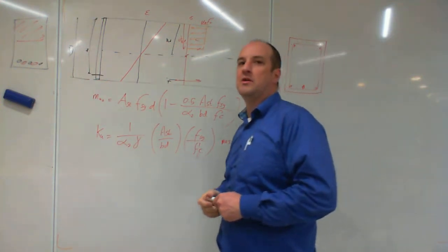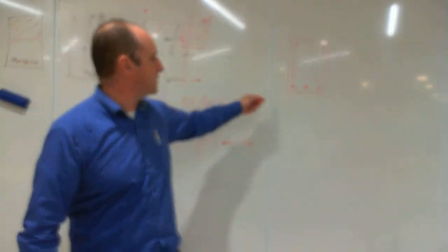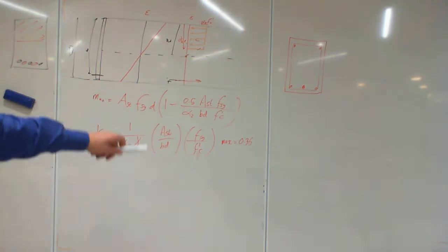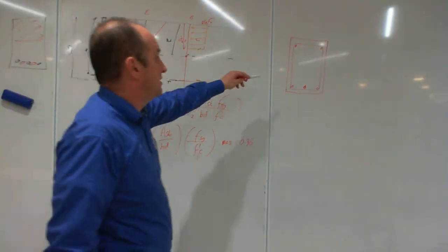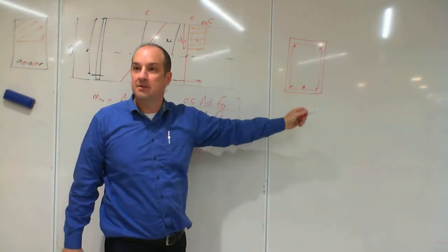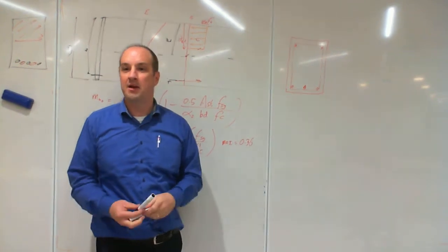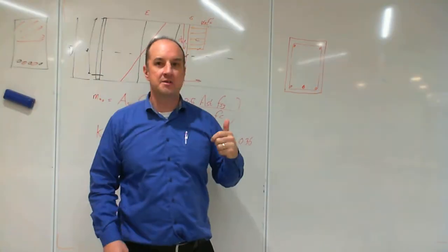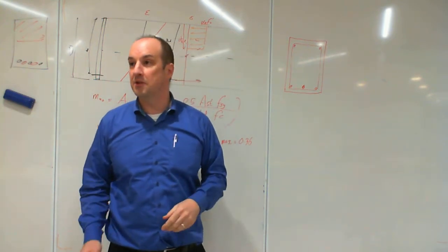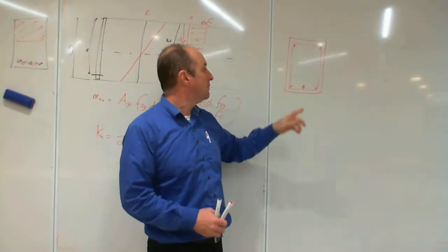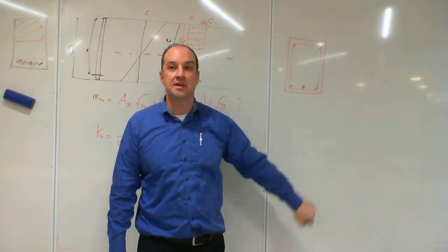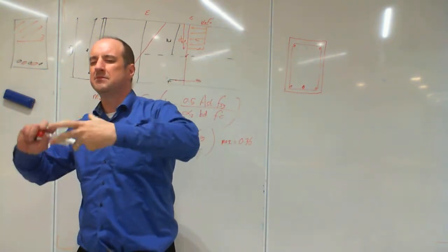So you might think, why on earth are we just talking about singly reinforced beams when actually there's always top steel? Okay. First, the rings. Anyone know what they're for? Okay. The rings, they're also called stirrups. They're to resist shear force. Okay, you'll learn about them when you get to the shear force one. But they do shear force and torsion, and they hold the concrete together.